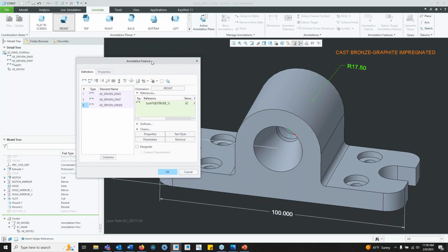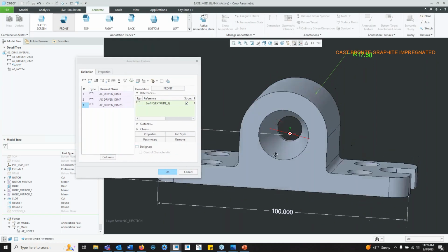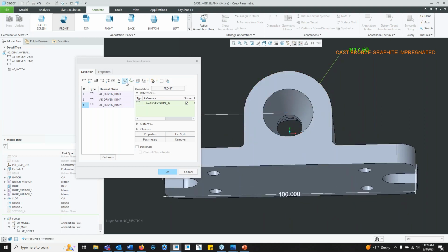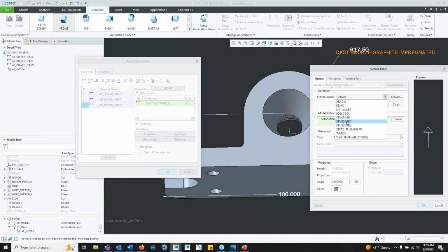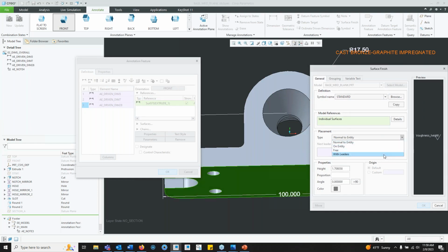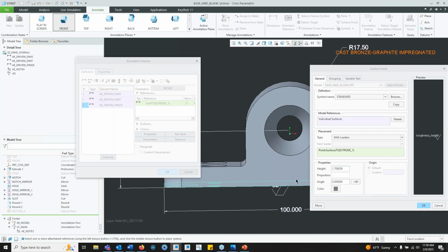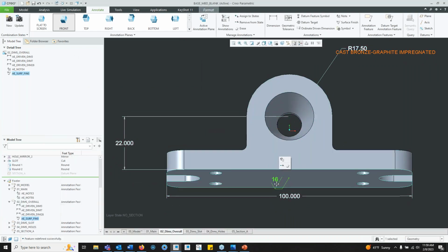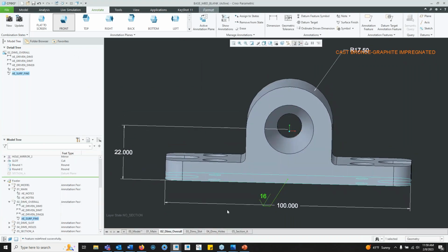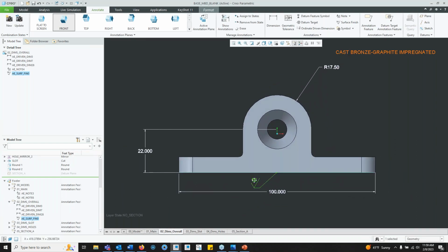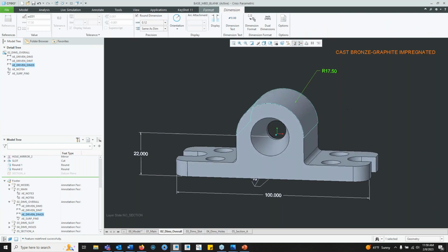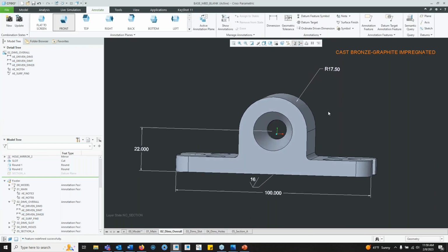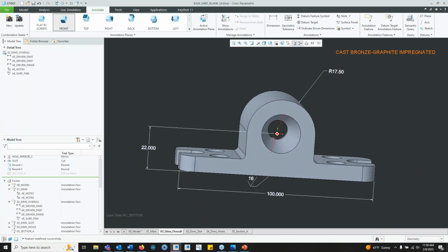If I wanted the surface finish symbol at the bottom, I could choose this here. I'll do a standard one, and I'll do this one with a leader, and I can move that when I'm out of this window. What's nice, since I already have an updated view, I could just hit that tab again, and now I have this. And so now you can see I'm starting to add dimensions pretty easily directly on the model, and we can see here how quick and easy that is.